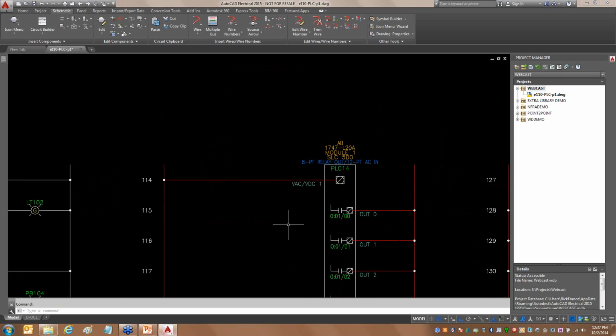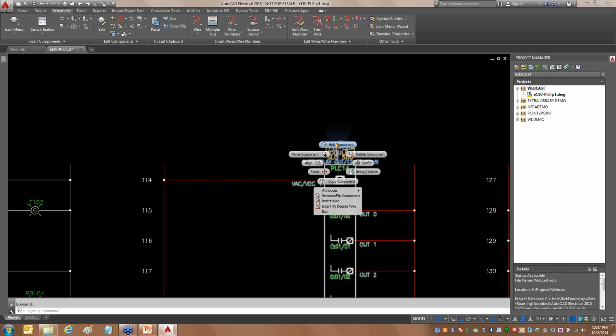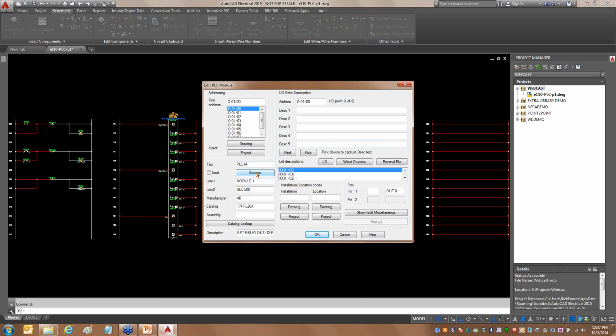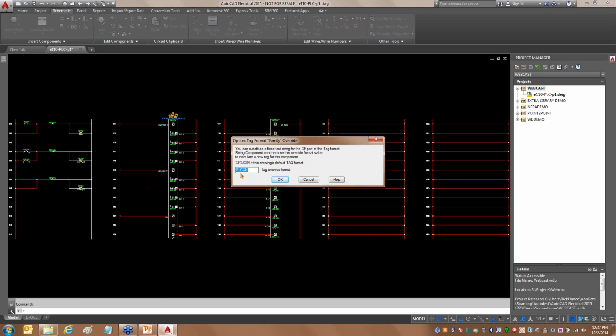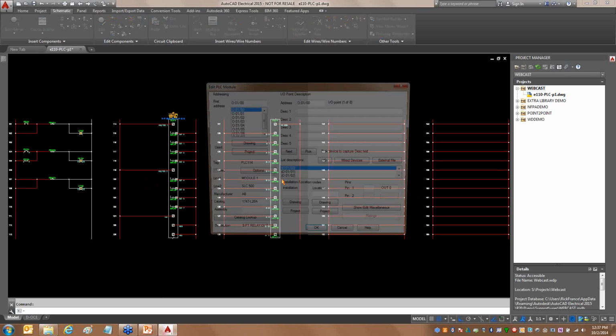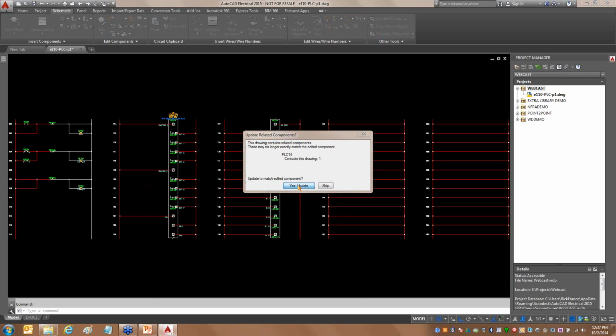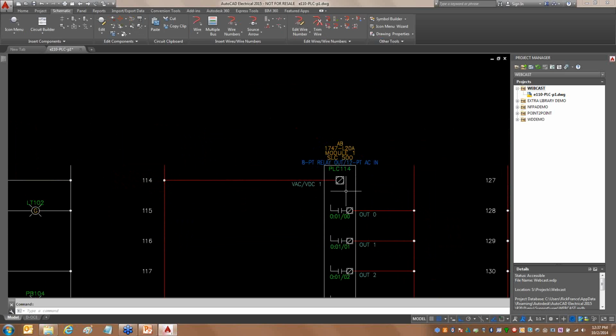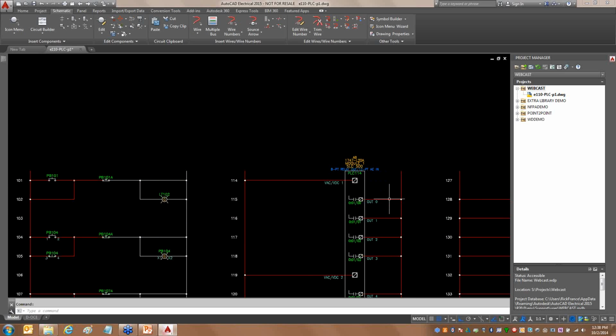However, my PLC came in. It's using PLC 14, which is just my rung number. It doesn't use my sheet number, even though I've got it set up in my project to use that. Now I can fix that on this one by simply going to the edit component and the options and seeing PLC %N. I'll add my %S, hit OK, and it'll update. So now it's reading correctly: PLC, sheet number, wire number. However, that was just for that one.